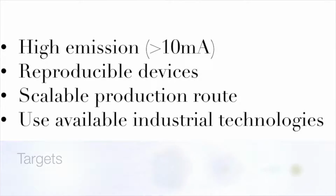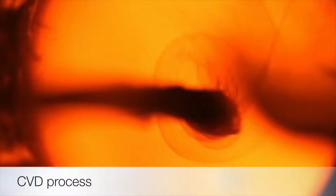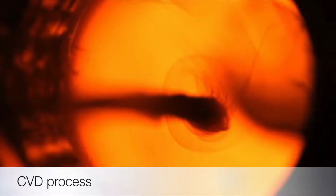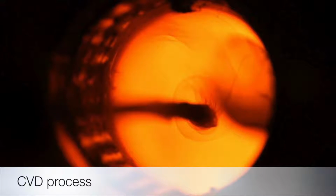The targets of this project are to have high emission, reproducible devices, and a scalable production route using available industrial technologies. I'm using carbon nanotubes because they have high current carrying capacities. The nanotubes are made at the Department of Material Science by a chemical vapor deposition process. On one side, we inject a liquid source of carbon and iron catalyst into a furnace, and a black cloud condenses as seen in this image.